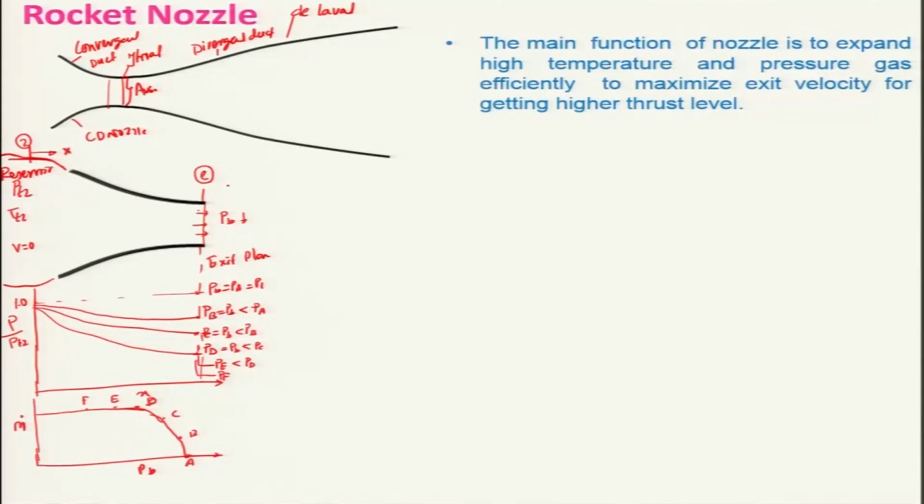keep in mind that this condition of the D, which we call the choked flow condition. At that condition, the Mach number at the exit will be 1, and the area corresponding to star is the choked mass flow rate condition, along with the density, temperature and pressure.